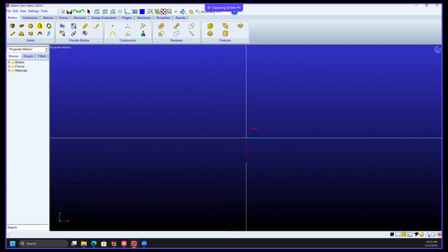The next thing you want to do is create your plane for the stone to fly on. So up here, rigid body box, you want to click on that. Where it says new part, put on ground. This is in centimeters, so we're going to have to convert it from our millimeters. The length of it will be 3,500 or 350 centimeters. The height is going to be 100, same as the depth, which is 10 centimeters.